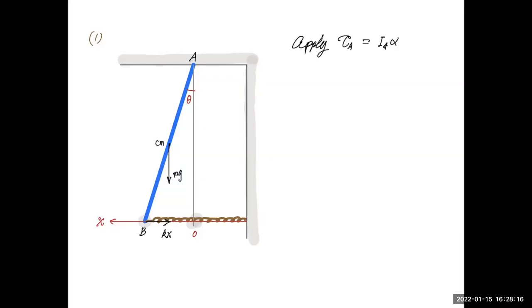Now, as you know, torque is equal to what? Force times lever arm. So here's a force, and here's a point of interest, in this case point A. You draw a line perpendicular to the line of action going through point A, and that is the lever arm. So torque about A equals F times the lever arm, with positive meaning clockwise and negative meaning counterclockwise. Now in this case, look at the torque provided by mg. Using this knowledge, let's do that.